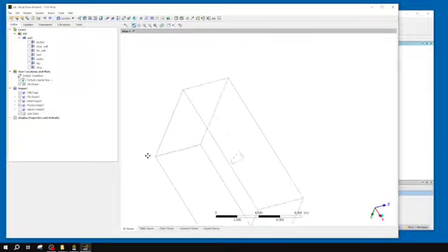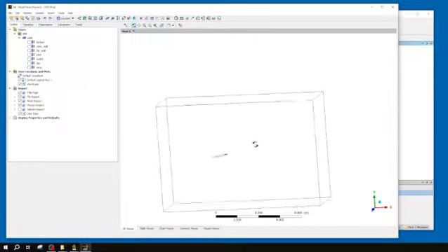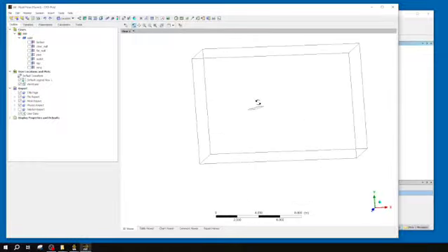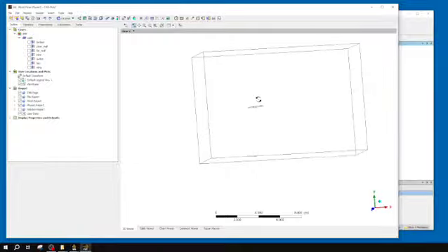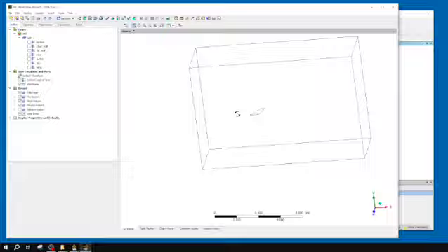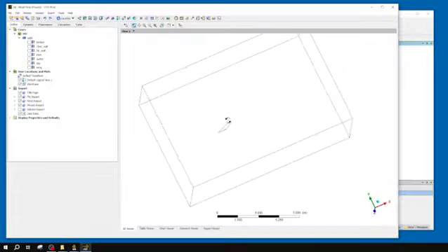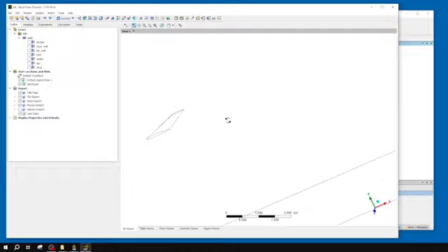So let's say I want to get in. So control, and that's control middle click. So your middle clicks do all your navigating. So yeah, middle click rotates, control middle click slides around, and then you can use your zoom wheel to zoom in on the subject. A couple other nifty things you can do for moving around this program.